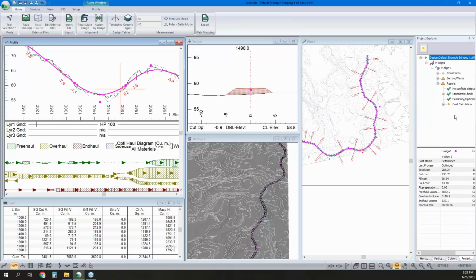Now before we go into the slideshow for that, I'm just going to expand this and we can see that we get this warning that we've got an underflow. So it's telling me that I'm 285 cubic meters shy on having that material that's Q3 or better, but at the same time, I've got an overflow. So I'm also cutting a surplus of material, stuff that I can't use there, and stuff that I can't use along the rest of my road. So this is a surplus of 2,700 cubic meters.